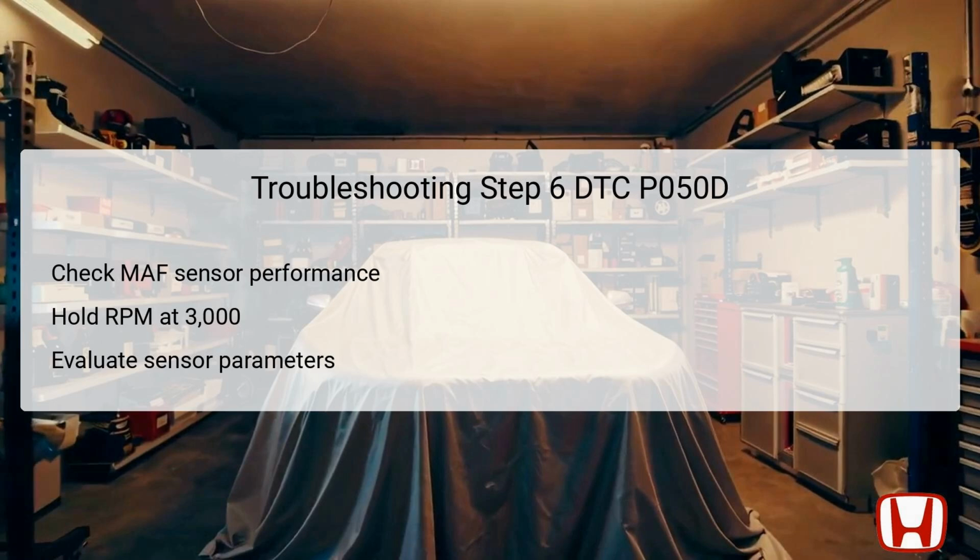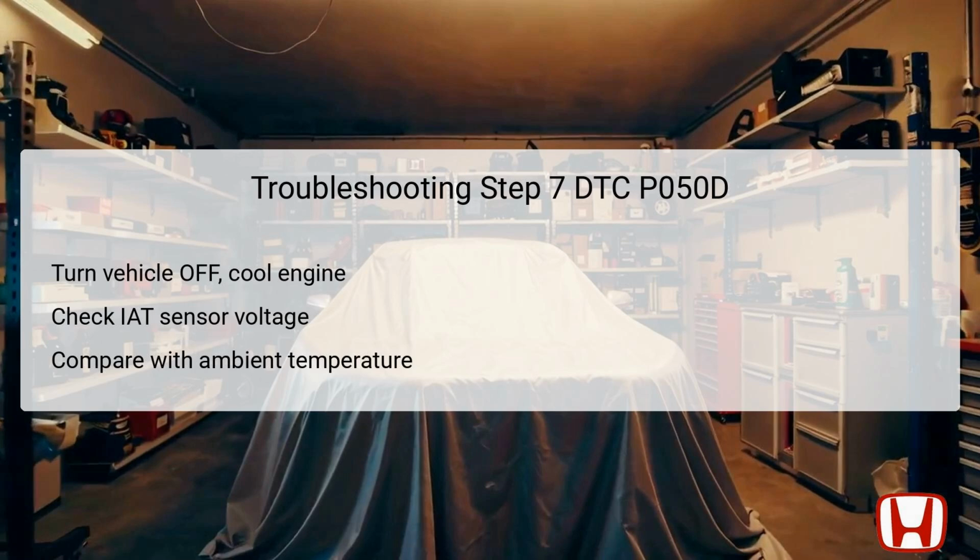Conversely, if the readings do not match, the MAF sensor or the intake air temperature (IAT) sensor should be replaced. Step 7 focuses on checking the readings from the intake air temperature (IAT) sensor. Start by turning the vehicle to the off mode to allow the engine to cool down to the ambient temperature. Once cooled, note the ambient temperature before turning the vehicle to the on position again.